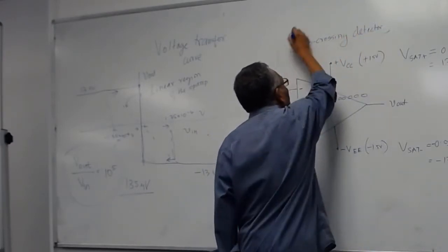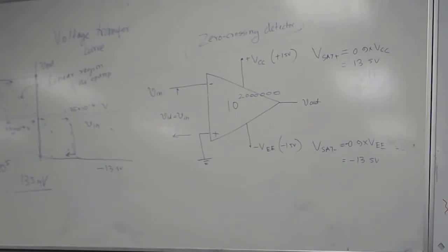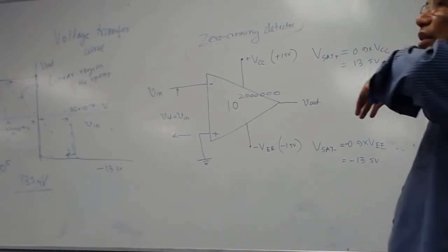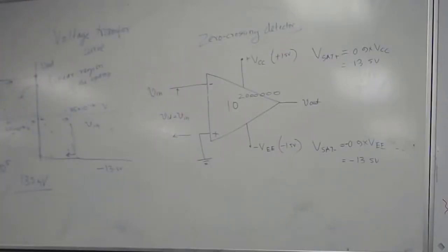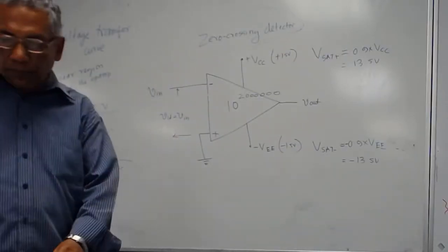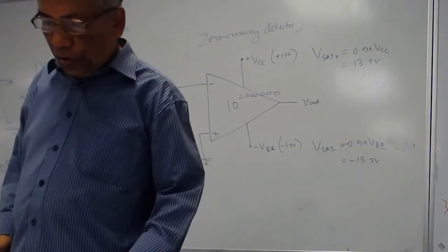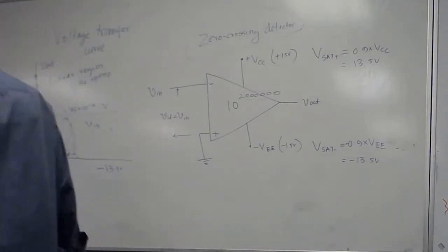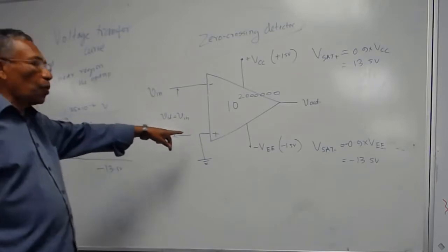Okay. So now we know a bit more about the behavior of the op amp. That it's really not an amplifier, it's really a comparator, and it can be used to detect signal levels, whether it is crossing 0 or 1 or some other level. Next is, how do you use it to detect a level which is not 0? You are trying to detect another level.